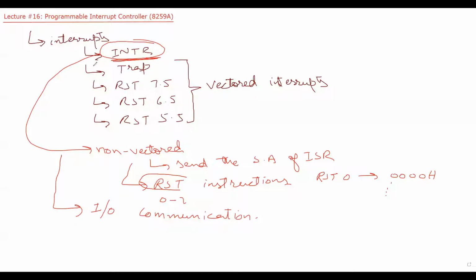Now, the limitation of INTR is, the first limitation is that there is a single pin for this, a single pin that can enable IO communication. So I can only connect one device to this particular interrupt pin.